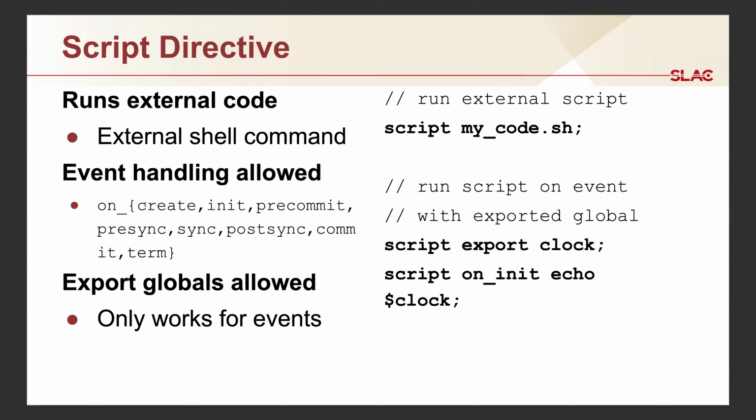There are a number of event handlers that exist. OnCreate is used after the GLM file has been loaded, but before the simulation initializes. OnInit is run after initialization is completed. Pre-commit is run before a clock update occurs.